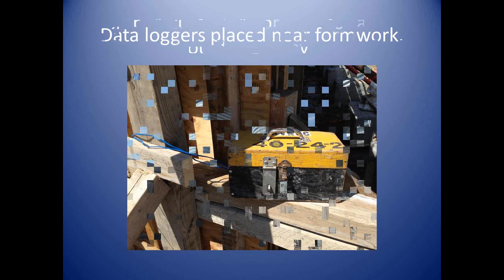Here's what it looks like when we took a screenshot of the HOBOware software when we brought the readings into the computer. And this is the data once we got it from the thermocouples. We input that into Microsoft Excel. And you can see the blue is ambient. And white, green, and red are the top, middle, and bottom of the slab. That's where they were installed: top of the slab, middle of the slab, bottom of the slab.